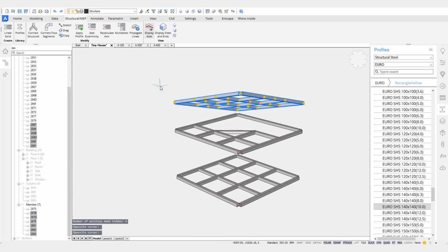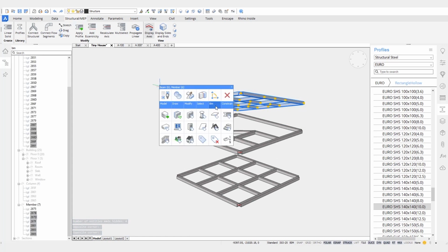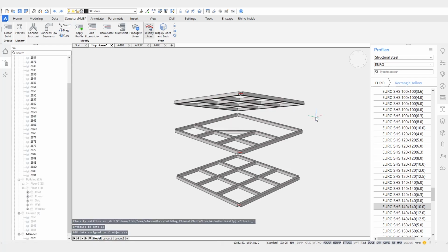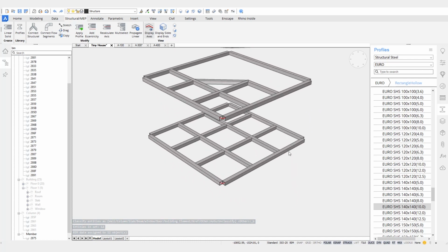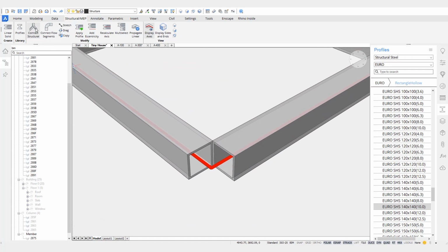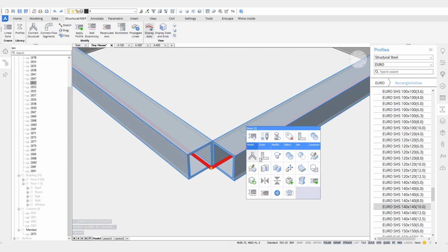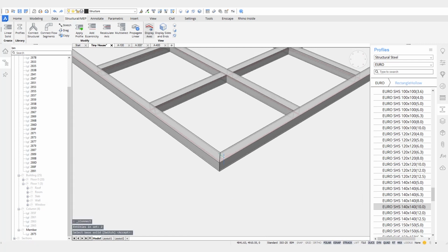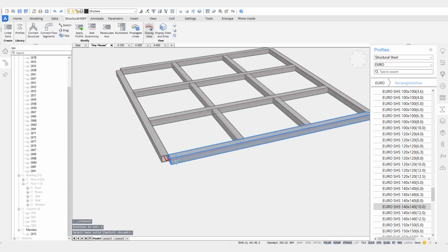I would suspect that this could be prefabricated, so these 3 objects could be prefabricated off-site and then assembled on-site using these columns and welding them together. So we want to have some welded connections for all these beams. Let's just make sure they're all classified as beams. So we can create this simple mitered connection like this using Alconnect, or I can create a connection like this.